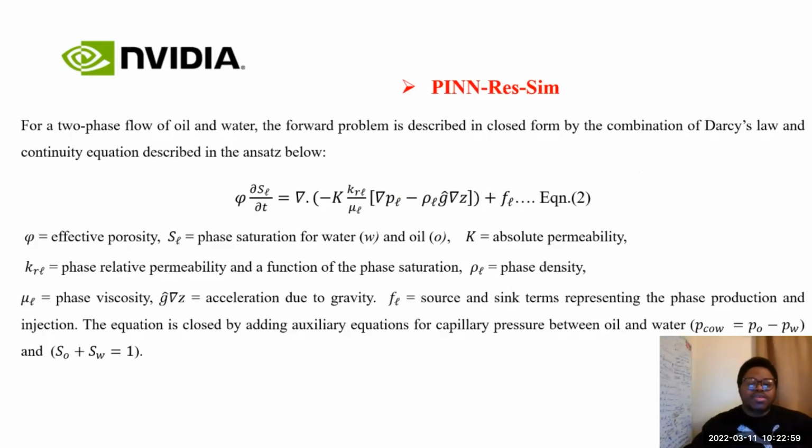This is the porosity, and S is the saturation. L is the number of phases, which is oil and water. The nabla is acting on this left-hand part, which is our T matrix. If you remember, this is the transmissibility matrix, and it equals the effective permeability times the relative permeability divided by viscosity. The relative permeability is a function of the saturation using two-phase rel-perm curves.